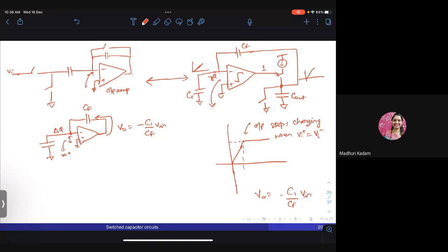For example, one simple thing you can do is use one differential amplifier, or maybe even 2 in a chain. I'm showing it with resistances, but you can use any transistor based circuit also. And then you can just use an inverter to take it to rail to rail.